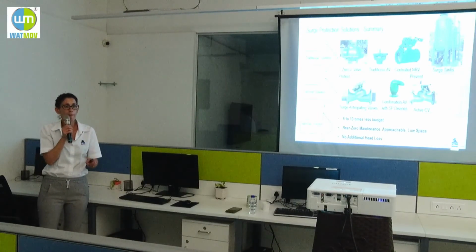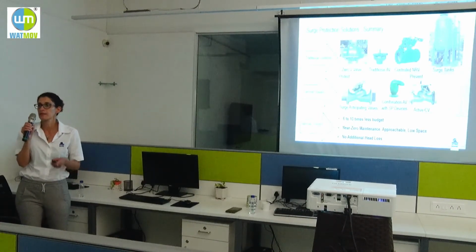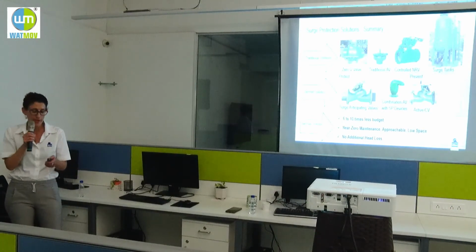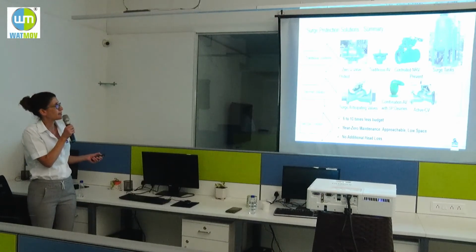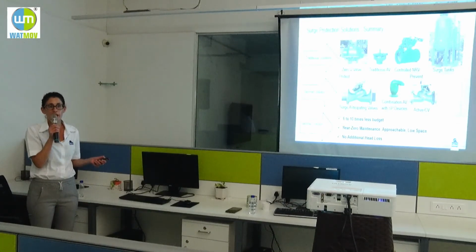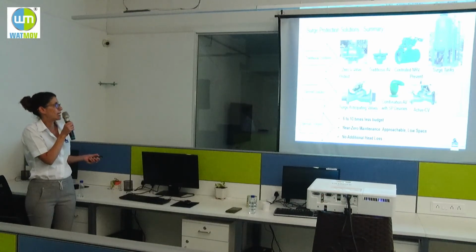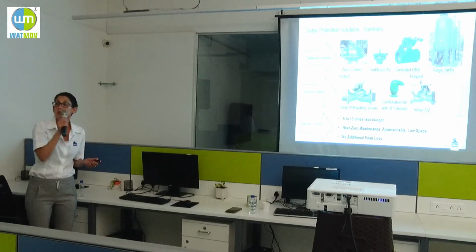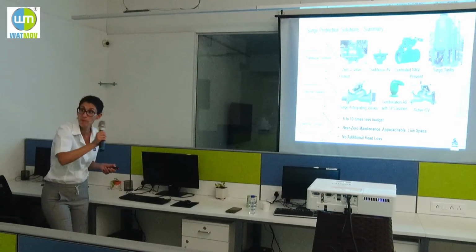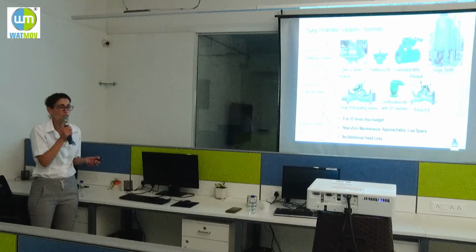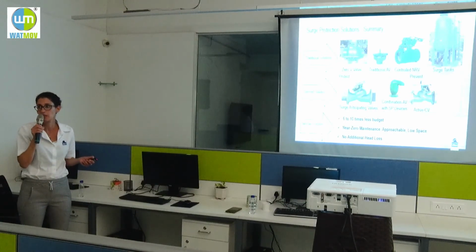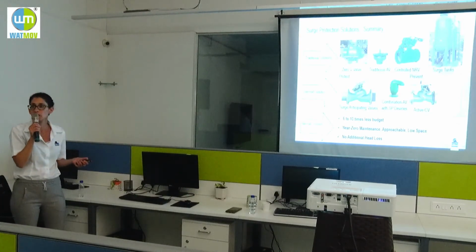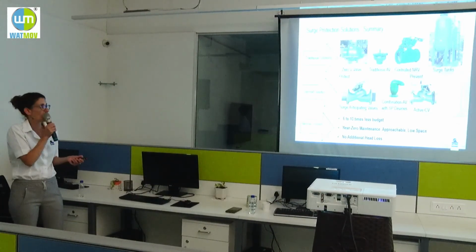So just a short summary of all the solutions, traditional solutions that we can see in India compared to the Bermad offering. In India we see zero V valves, which are like a very quick check valve. We see traditional air valves, controlled NRV that allows us to let the water go backwards towards the pump in a controlled manner, and the surge tanks that we all know. And the Bermad solution, a combination of surge anticipating and air valves.